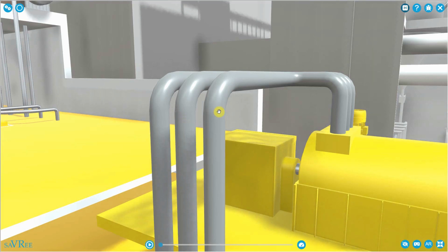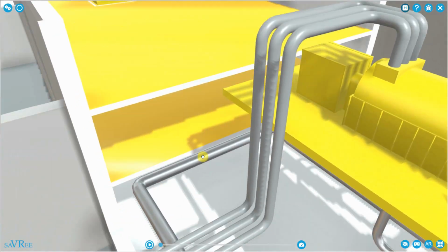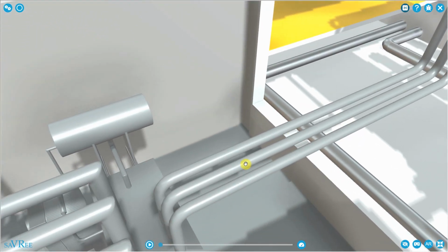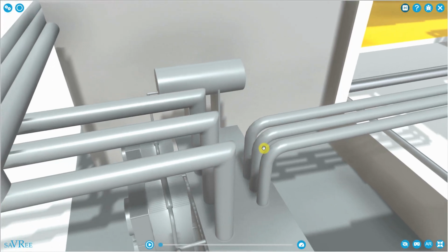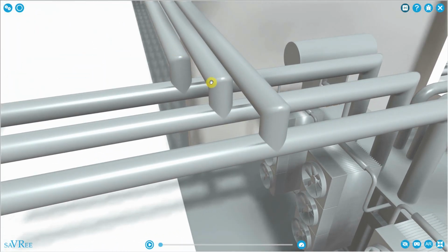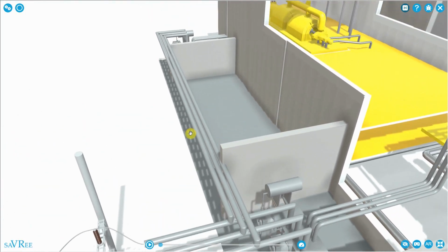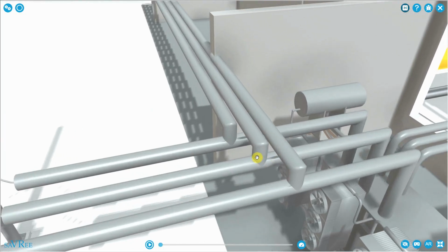These pipes are charged with insulating gas. SF6 is a common insulating gas. So we take the electrical connections, the bus bars, out from the generator within our insulated piping connections, and we connect them via bushings to our electrical transformer. From the transformer, you can see we've also got connections coming from the other transformer, which is connected to our other steam turbine. They connect together here.